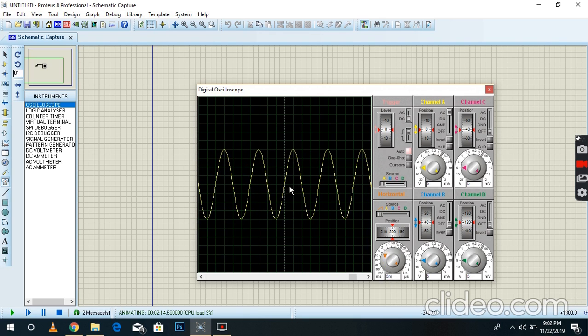So in a single time division it measures 5 milliseconds, here 10 milliseconds, 15, 20. For this sinusoidal signal, 20 millisecond for a cycle time means 50 Hz frequency. 1 over 20 millisecond is 50 Hz. So you can have a clue of the frequency from this graph as well.